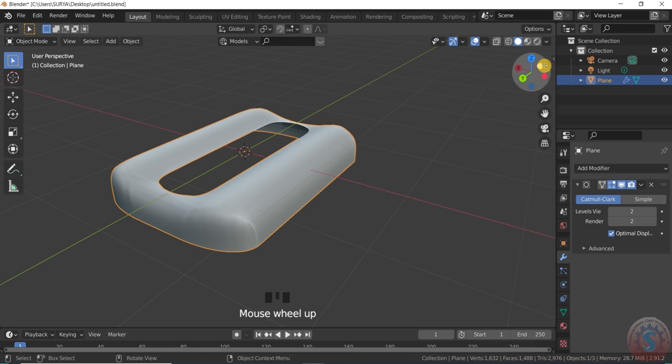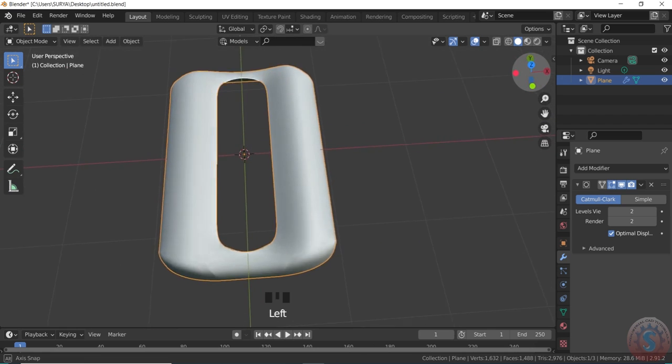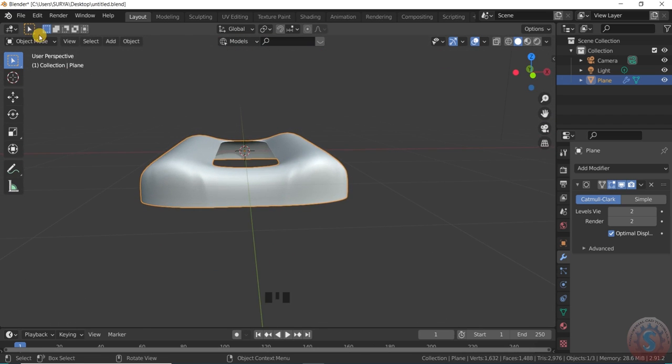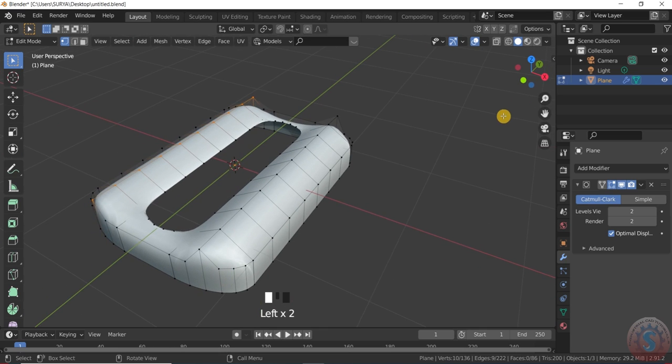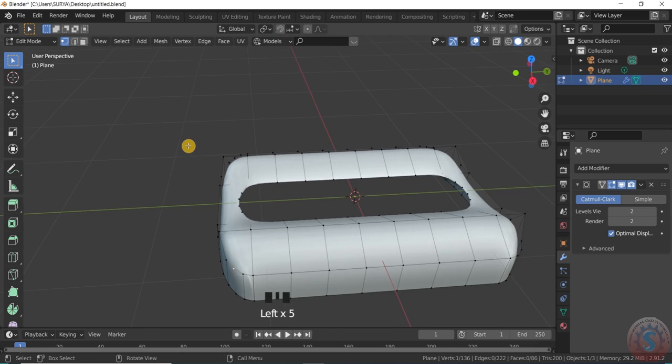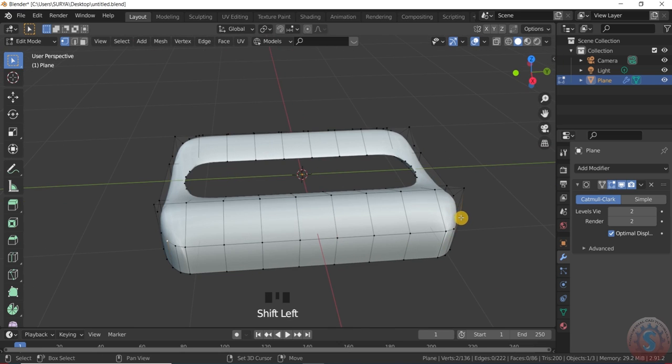One is the knife edge topology, one is the connect vertex path. Both are the same, you can use either. Then after, I want to combine the vertices by using the connect vertex path. Follow the process.